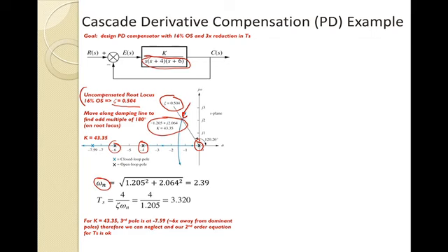So what we found previously, we'll switch colors here, is this length. This length is omega n, and this angle we can call theta, and the cosine of this angle was indeed the damping factor zeta that we saw here. So I'll just write that down real quick. Cosine of that angle is basically our damping. So we can find omega n, shown here, just with the Pythagorean theorem. We know this base, we know this height, and the square root of the sum of the squares gives us omega n. That's what I'm doing here on the graph.